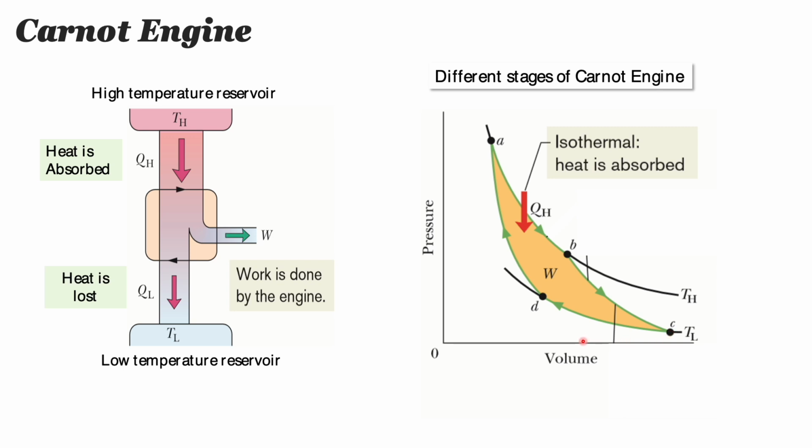So that means the gas has expanded from here to this value, but without any transfer of heat, without absorbing any heat. If it is expanding without any absorption of heat, its temperature will drop. Now this temperature has dropped from TH to a new value TL, because it is in contact with TL also. It cannot go below this because it is in thermal contact with this. Now when it arrives here, this process has taken place, going from state B to state C